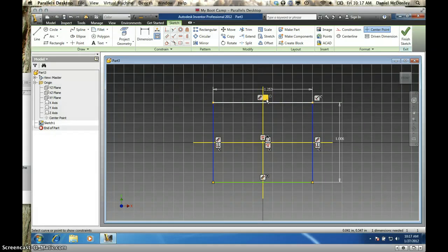horizontal constraint. Well, it's already horizontal, and these are already parallel, so I really don't need that one, so I'm going to delete that. This is also a perpendicular constraint. Well, everything is already parallel, so if those two are parallel and those two parallel, we're fine. Let's get rid of that too. And so now we actually have our green thing here. Let's see if we can get our constraint again.